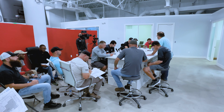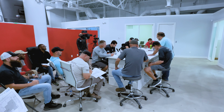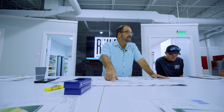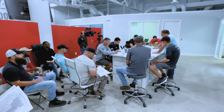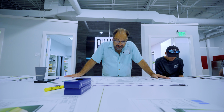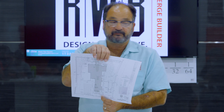That brings a bunch of issues to head. One is if I alter the grade to keep a shorter wall, now you've got to look at the impact of how it affects the driveway, how it affects the grade, how it affects the drainage. So you look at these and you find things like that. On the south side or on the bottom of the plan, you'll see a site wall. And it says top of wall 20. Right here. Everybody see that?